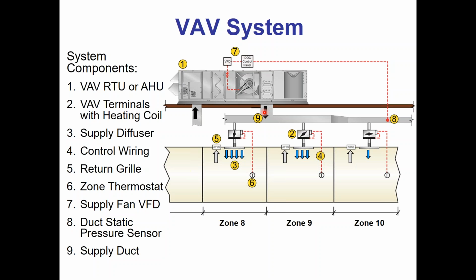That means you're at a design day for weather and a design day for occupancy. So that hardly ever happens. So whenever, as a controls person, you see 100% on the VFD, it's a red flag that something's probably not right. Normally, you're going to see things operating 40, 50, 60%. It's kind of the normal range of a day-to-day operating VAV system.